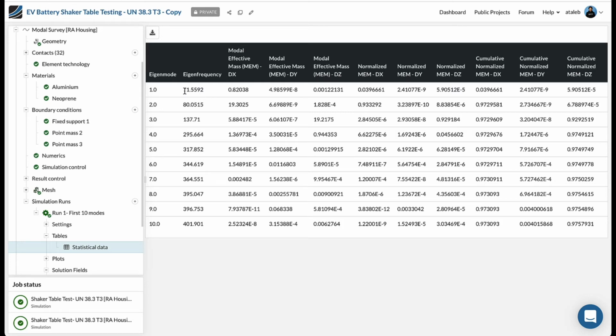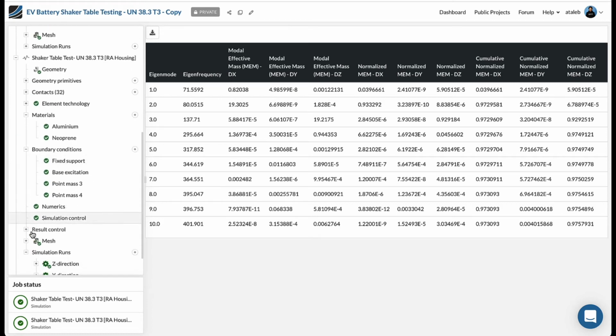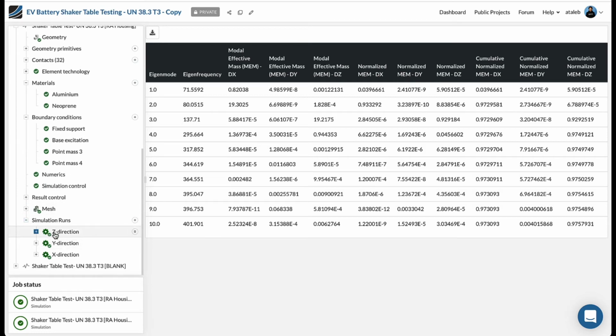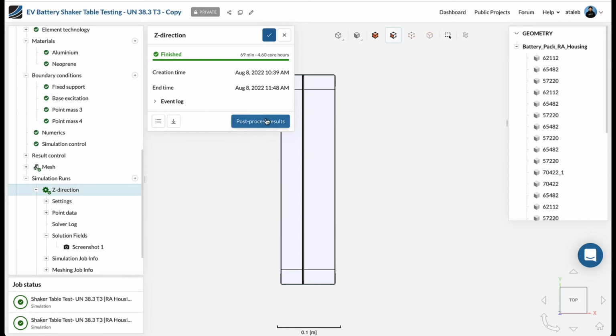In the physical test, we will be going past 3 different resonance cases, which can lead to very high amplitudes of the vibration response. So that can be quite problematic. And we can now go into the results of the shaker test itself, and we'll look at the Z direction because that is the most problematic one.